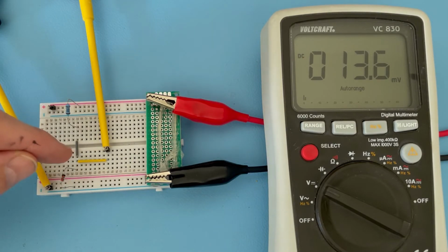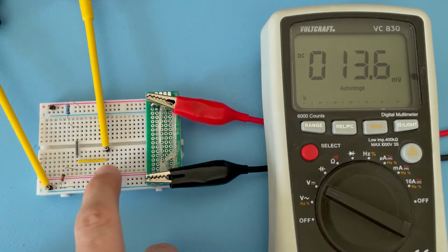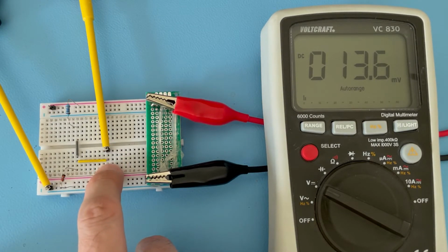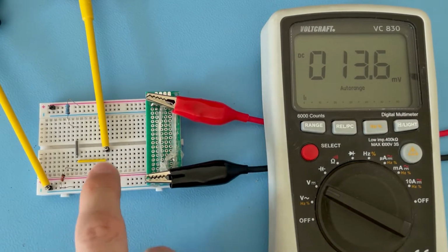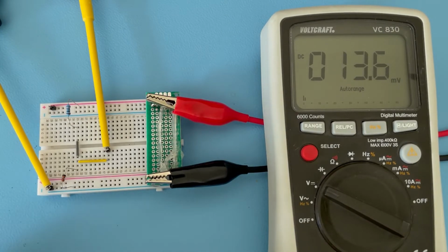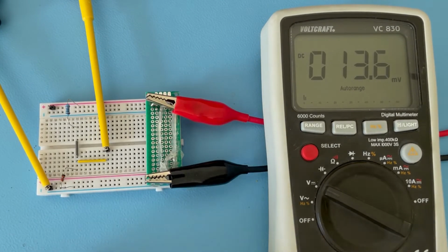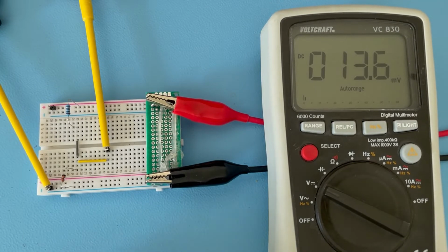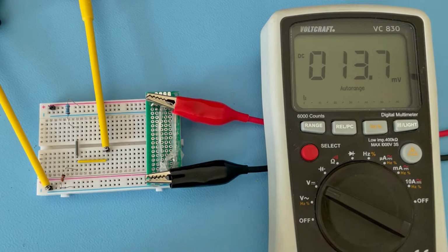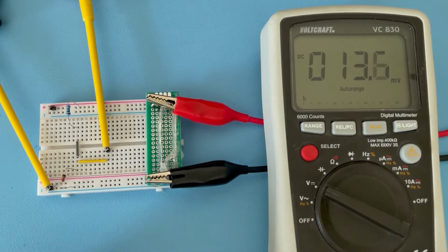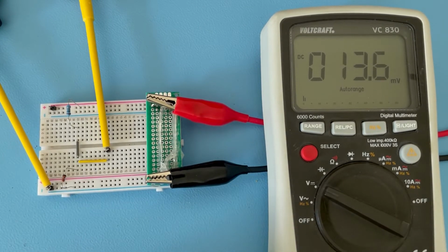Before the Zener, I have this yellow wire attached, which I measure with this little pin on my multimeter. What is the output voltage here in the middle? At the moment we have no load connected, so this should go pretty well. So let's switch on the power source. I have made it a 9 volt power source like we drew it, and my power source can limit the current, and I have limited it to 100 milliampere, just so things don't go completely wrong.